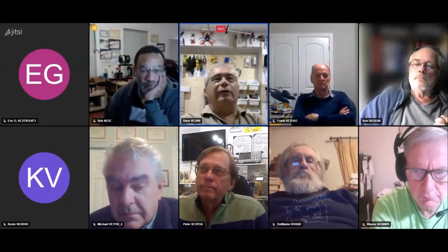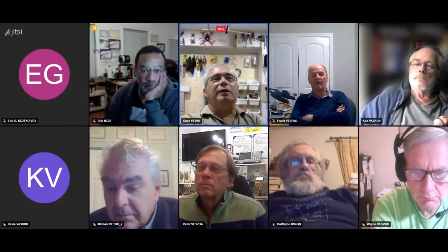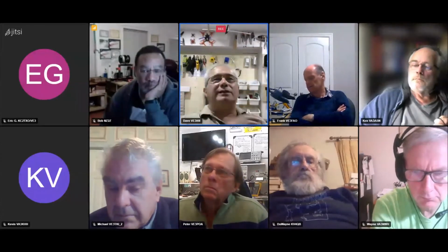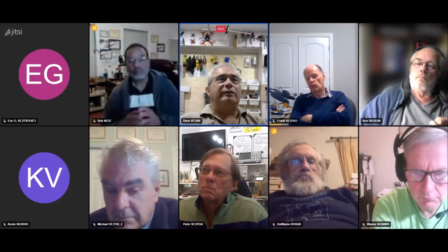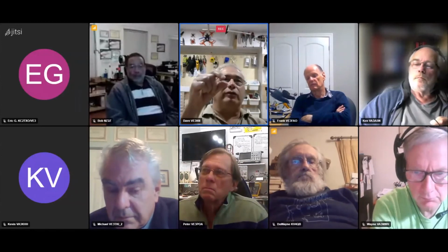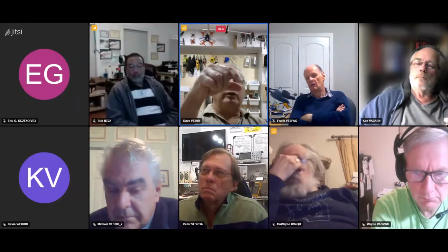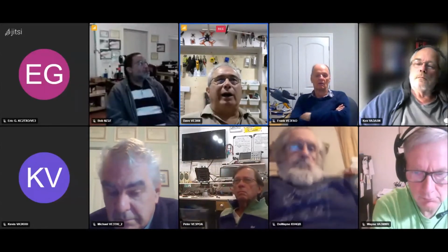Charlie's got a really good way of characterizing filters. If you think about it, it's actually pretty smart. He builds a resonator, a Colpitts oscillator or something like that, and it's built exactly, he doesn't change anything. He unplugs a crystal, plugs another in, and leaves it running for a bit to warm up.